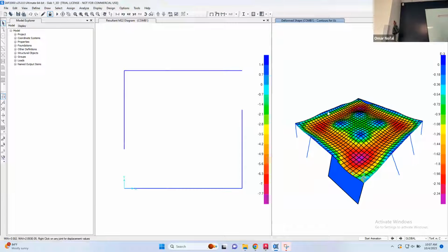All right, so what happened here right now? Can you guys explain? I should put supports on the column. No, but why is it stable? This one looks not stable, or this one is stable, by the way. I'm saying it has a weird deformation. But what happens here is that we didn't remove the supports that we already defined for this slab. We have it from our previous model.